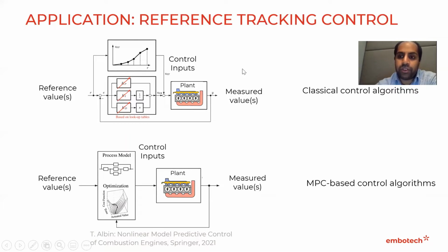If you now substitute this by an MPC-based controller, then you don't have the division between feed forward and feedback anymore, but you replace it by the MPC, and the MPC contains the process model and the optimization algorithm, and this calculates your control inputs.